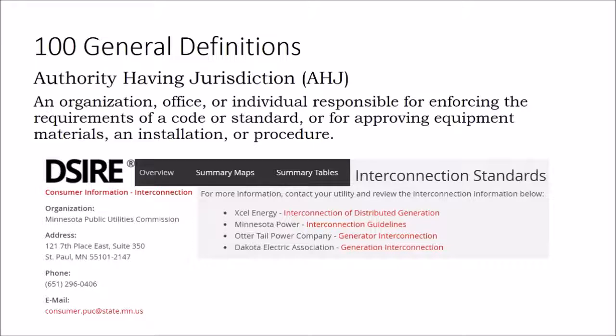So whenever you're doing any kind of solar design, if you design to the National Electric Code, you can still make design errors and fail your inspection because there may be additional jurisdictional requirements that you have to abide by. And so where do you go and find what your local jurisdiction is?